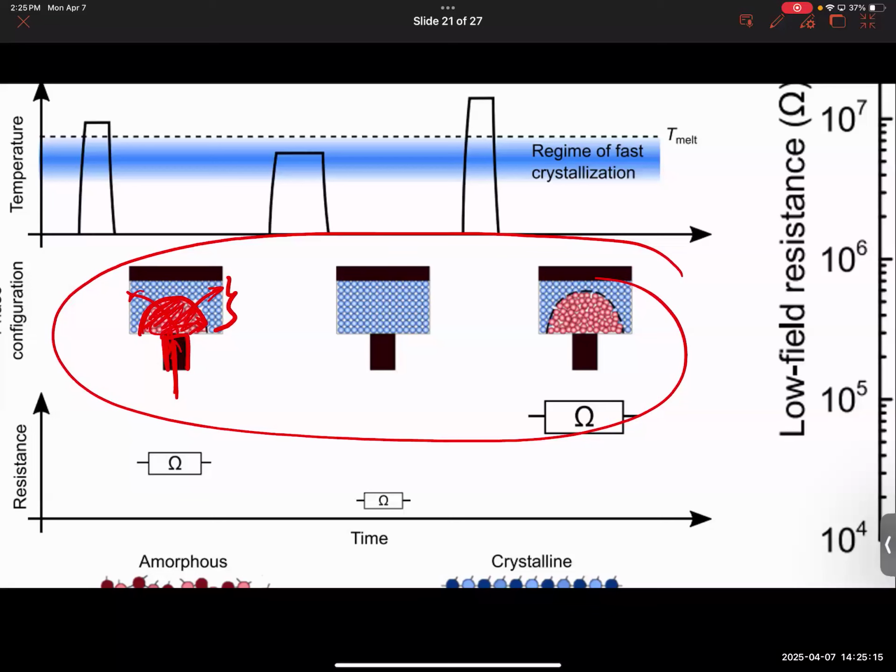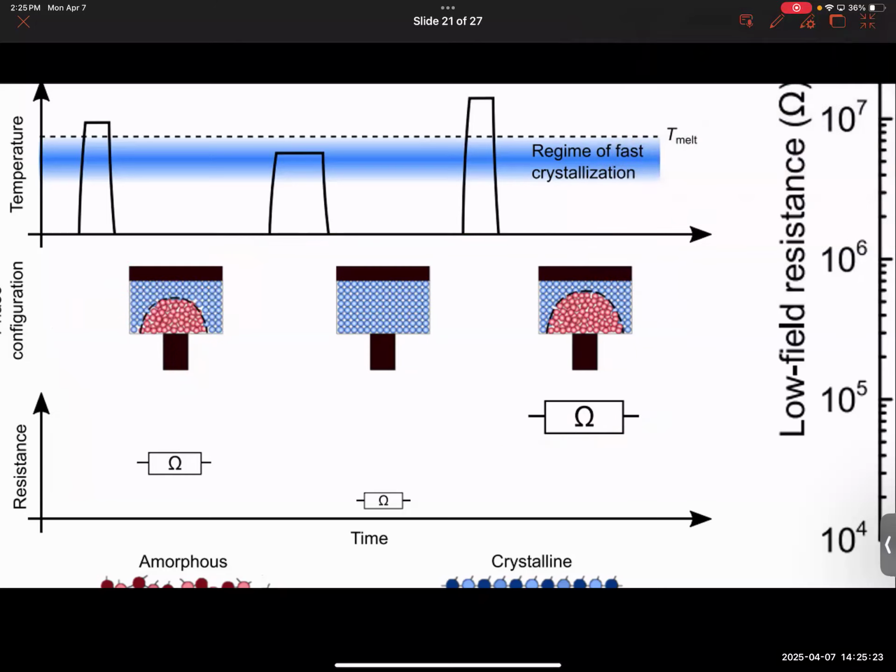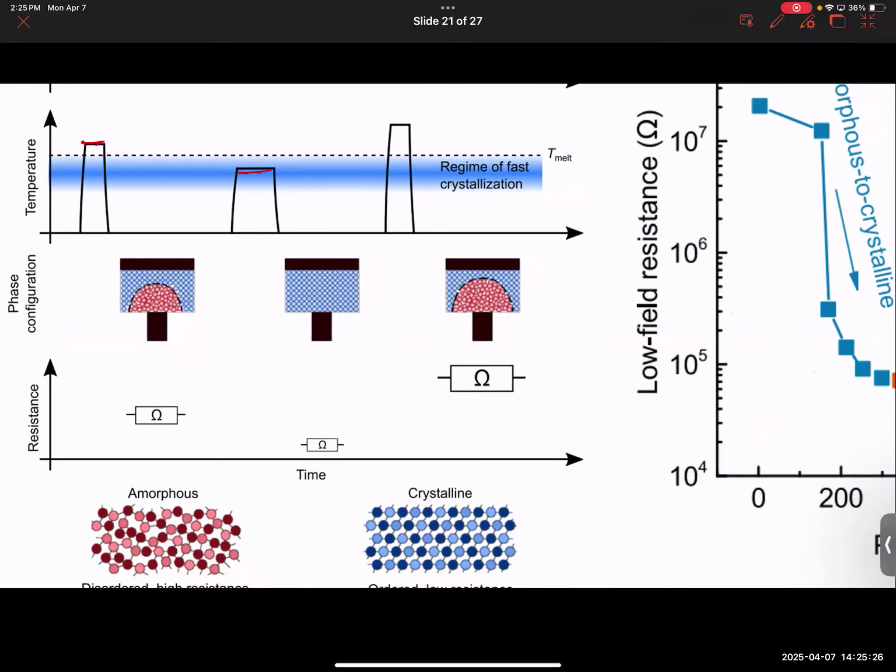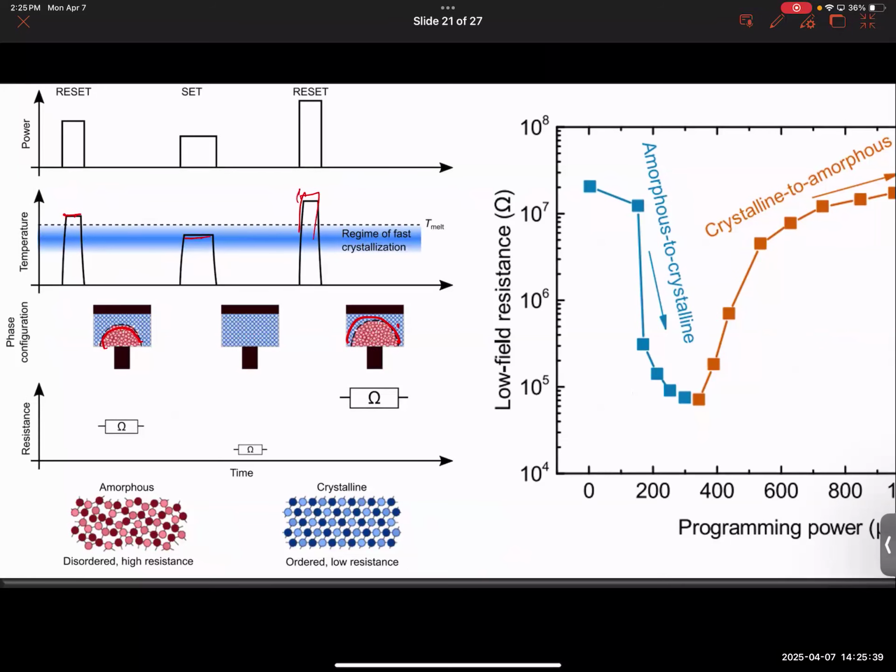So the more heat you provide, the farther spread out this sphere becomes. So by controlling the current level from being really high to medium to even higher, you could switch a small portion to a bigger portion. And by doing so, you could change the resistance levels. Does that make sense? And interestingly, for phase change memory, you don't have to do it in 4 steps. You could do it gradually, like really nice analog fashion. Instead of just saying we have 4 levels, we have many levels. Are you guys all good with me so far?